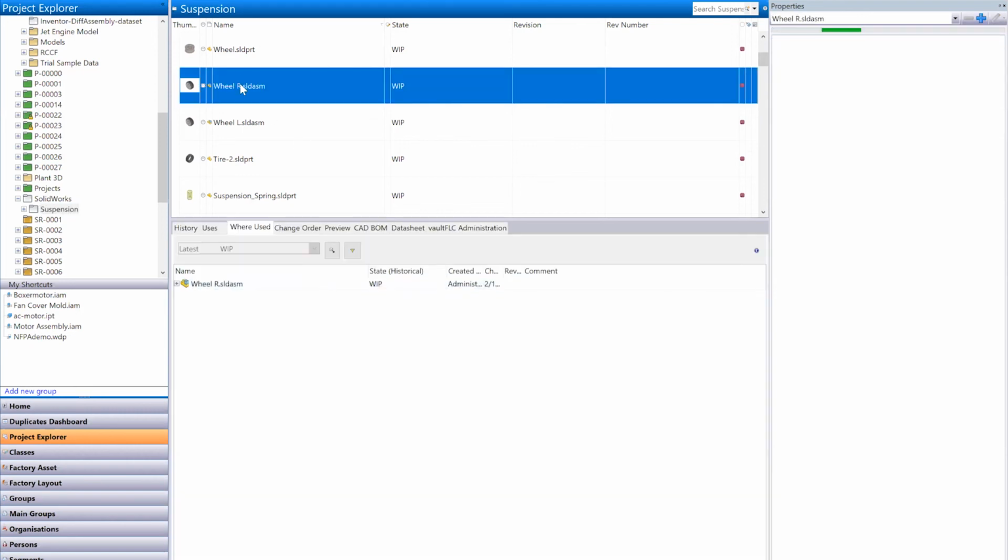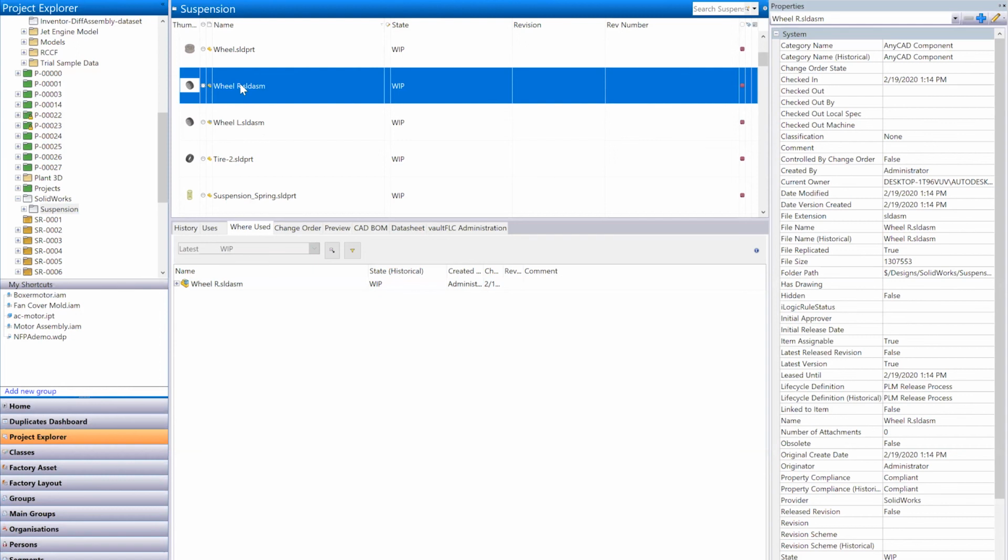Like the structure will look the same, but when you go ahead and download them, those relationships end up being lost. Or even if you move them within Vault to a different location, if they were uploaded properly, it maintains those relationships. It knows that this subassembly is part of this main assembly, and it corrects those relationships. If you add them through the client and those relationships break, well then you just have a bunch of different parts that don't know they belong to each other. So it's important to upload and to check in your files properly there.